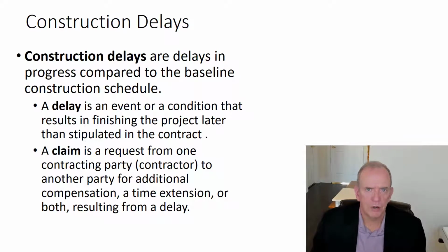In lecture 6A, we talked about change and getting a change order signed off. Well, we might see that there's a delay, maybe caused by the client's consultant, and I'm the GC, and I see this is going to delay us by a month because of a design error by the consultant. I'm going to be looking at how much that delay is going to cost us as a general contractor. We've got to have our site team here another month, the trailers here another month, our infrastructure here another month. There's generally a per diem cost of running the project. So if it's $10,000 a day and it's 30 days, that's $300,000 potentially for a claim. And it doesn't take that much on larger projects to get into that kind of money, and lots more per day. So that would be a claim.